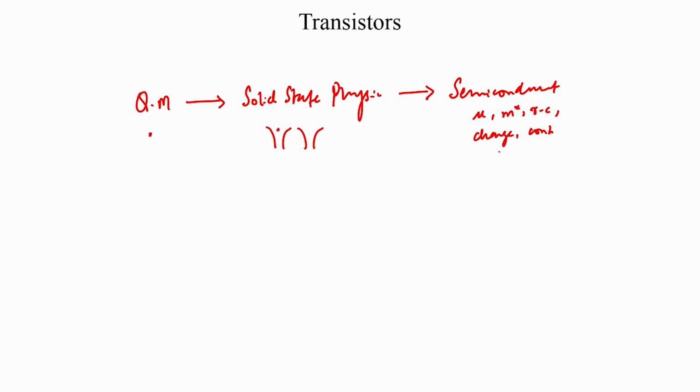And then we continued with our journey towards looking at junctions. This was a very important step wherein we looked at two kinds of junctions, the metal semiconductor junction and the PN junction, and we saw the tools and techniques of solving for electrostatics using ideas like the Poisson's equation, and then using the continuity equation to identify the current voltage characteristics, etc.